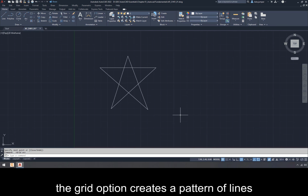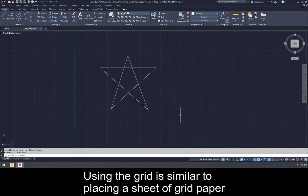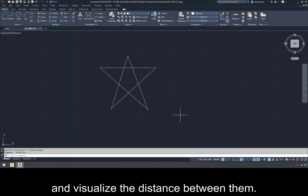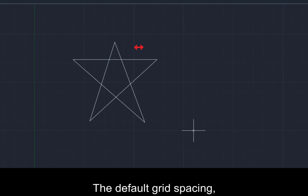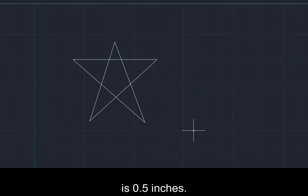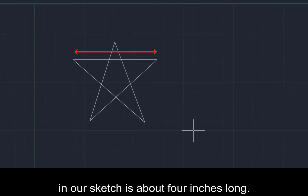The grid option creates a pattern of lines that extends over an area on the screen. Using the grid is similar to placing a sheet of grid paper under a drawing. The grid helps you align objects and visualize the distance between them. The grid is not displayed in the plotted drawing. The default grid spacing, which means the distance between two lines on the screen, is 0.5 inches. We can see that the sketched horizontal line in our sketch is about 4 inches long.